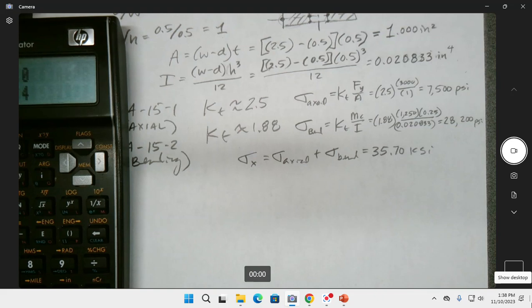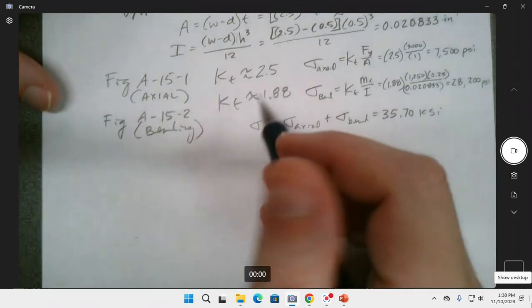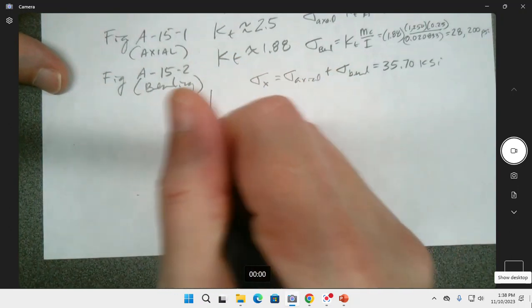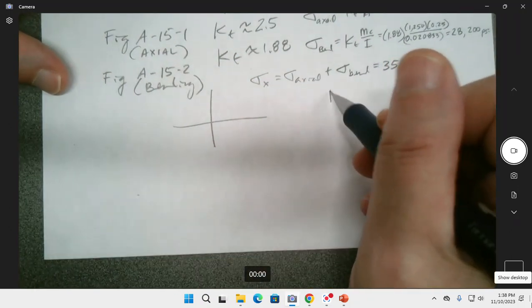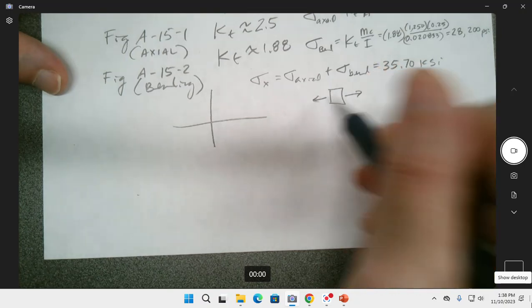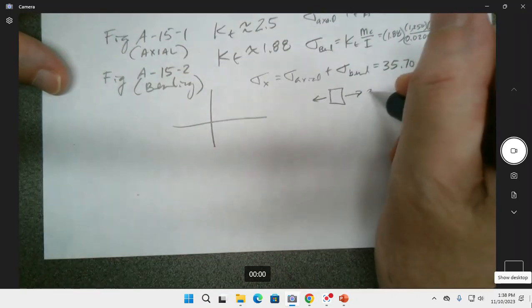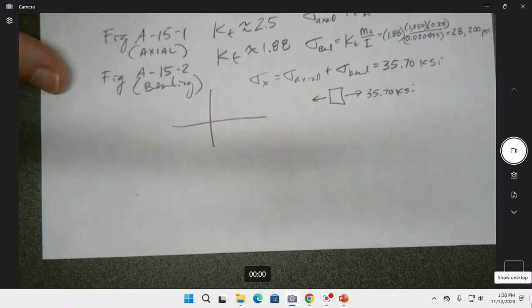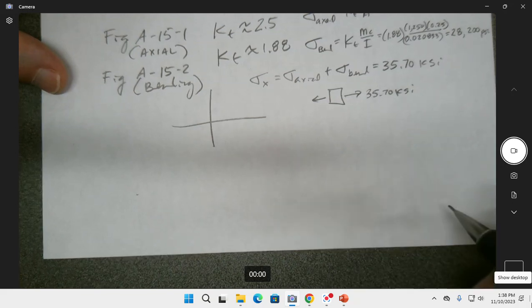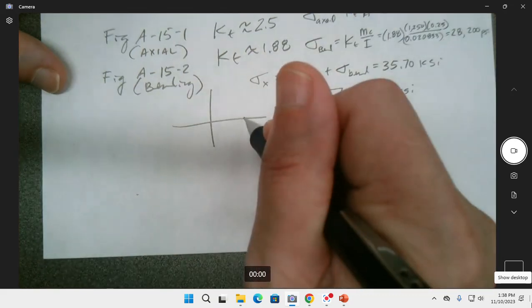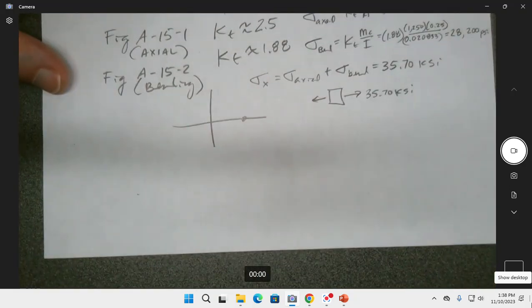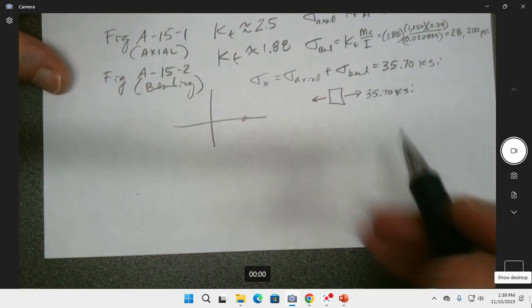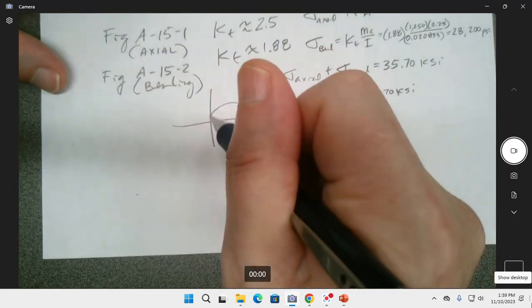And so if we want to go maximum shear stress theory, we need to get the moment. Oh, before we do that, that's the stress element, right? Is there any stress in the y direction? No. Is there any shear? No. So Mohr's circle is pretty boring. That is Mohr's circle. Now you want to do 3D Mohr's circle? There you go. Boom.